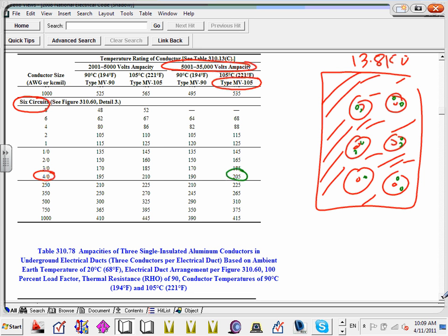What happened to the insulation? Insulation deteriorates. And of course, it's twice as expensive, guys, to put a medium voltage cable underground than to put it overhead. That's why the utilities, the cheapest, bring to your house and mine and all the stuff, they put it overhead. Twice as expensive to put the same feeder underground versus overhead.